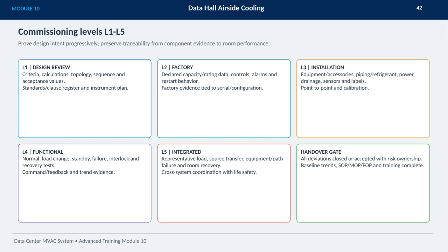L4 focuses on functional testing under various scenarios, such as normal operation, load changes, standby modes, failure conditions, and system recoveries, backed by command and feedback data. Finally, L5 is the integrated phase where the system is tested under representative loads and source transfers, including equipment failures and room recovery, ensuring cross-system coordination with life safety.